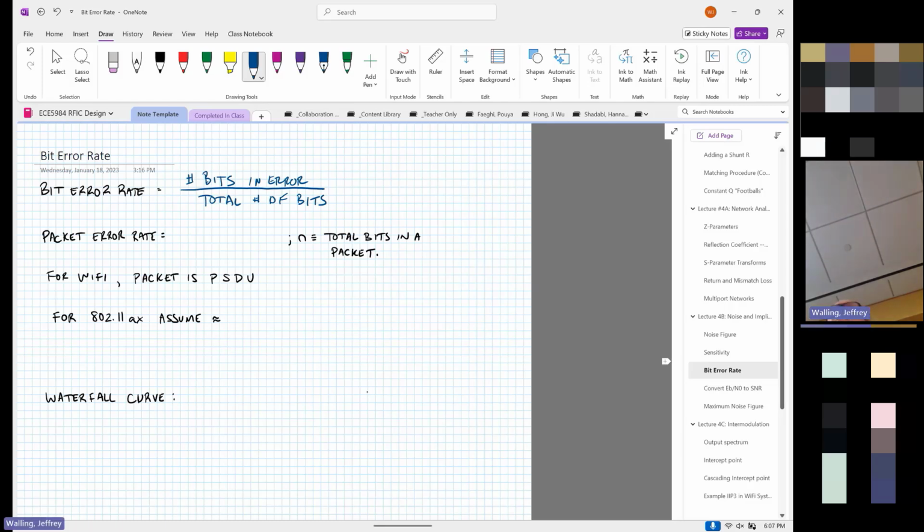What's the worst bit error rate you can possibly have? 0.5. If my bit error rate's 1, if I flip every bit, then the worst is 50%, 0.5. That means you have a completely random distribution of errors that you can't possibly fix.